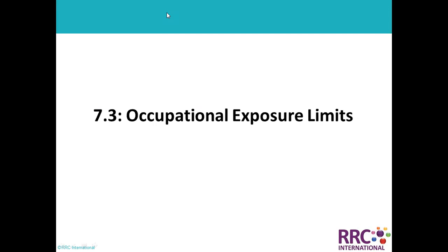Permissible exposure limit of H2S in a confined space. 1% is equal to 10,000 ppm, and 10%, what you mentioned, means 100,000 ppm. On the other side, 1,000 ppm is enough to kill a person in minutes. That means goodbye. Sure, you're absolutely right.